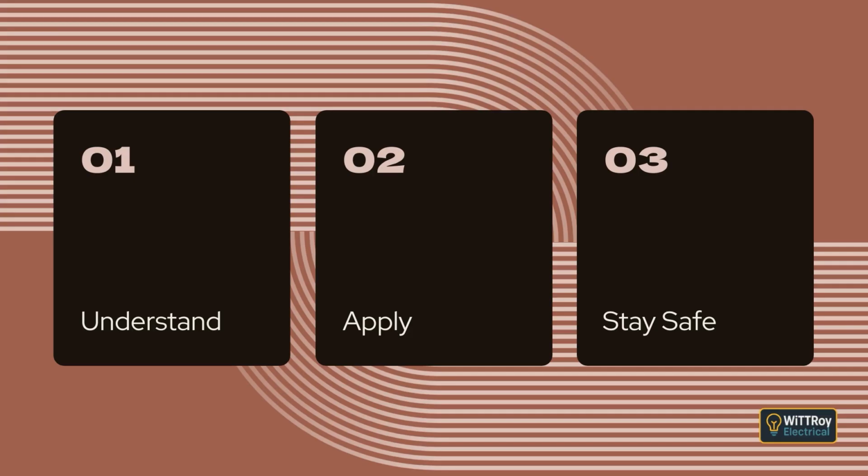Clause 3.10.3.8 Provision for expansion. Rigid insulating conduit must be installed with allowance for thermal expansion. As a guide, a 10-degree temperature rise causes about 1 mm of expansion per meter of conduit.